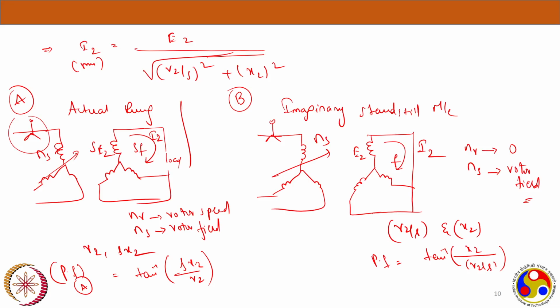They have modified the secondary side of the circuit to bring the frequency to the same as the input frequency, but the mmf should remain the same, the rotor field should remain the same, and the amount of current drawn should remain the same.